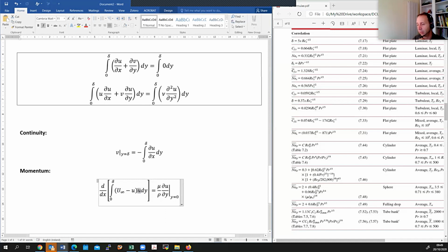You recognize the real velocity, you multiply by the hypothetical one that would be there without the boundary layer, and you look at the difference to what actually exists, and that gives you what is called the deficit of momentum due to the boundary layer. The boundary layer contains fluid that moves slower than on the outside. That's why we talk about a deficit in the momentum transport through the boundary layer.